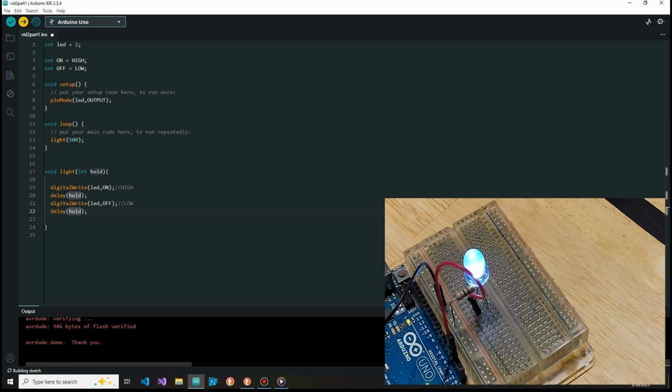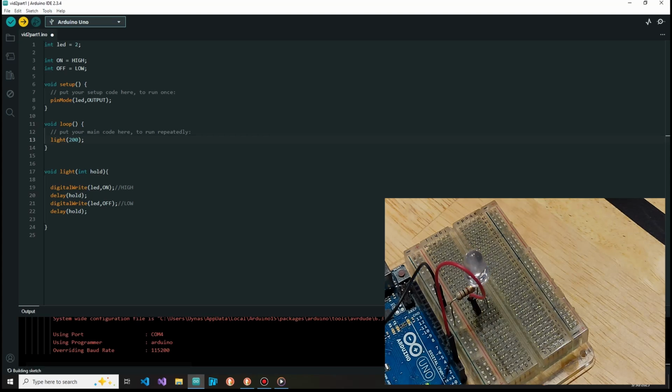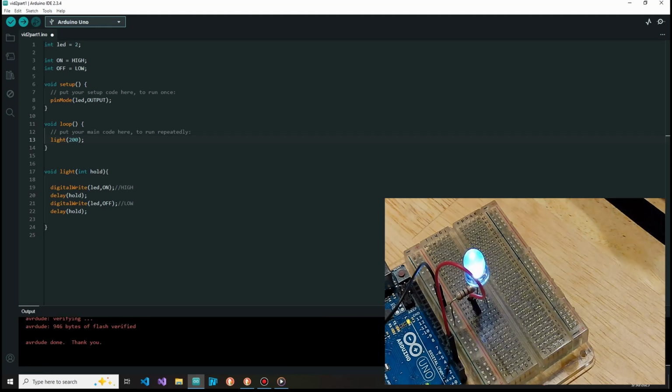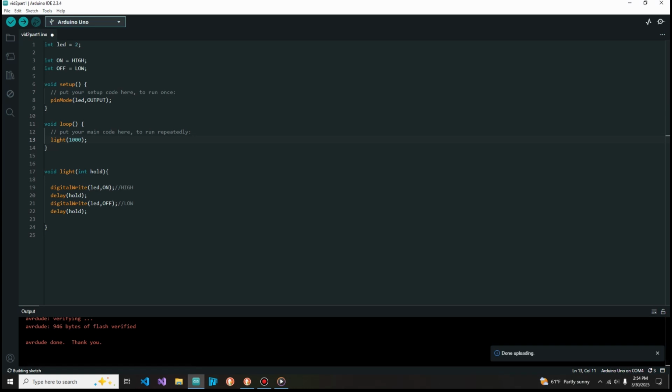We read our verbose, and now we're off. See, now it's still blinking. Now, if you want to be like, oh, hey, you know what? Let's make that run faster. Let's put 200 in there and let's upload it again. Now watch what happens. You changed one variable, and all of a sudden, just like that, we're up and going. If you want to slow it down, no problem. Let's put 1,000 in there. 1,000 milliseconds, so that's 1 second, right? So now off goes the verbose. It does uploading, and there we go. Isn't that impressive? That is really cool.